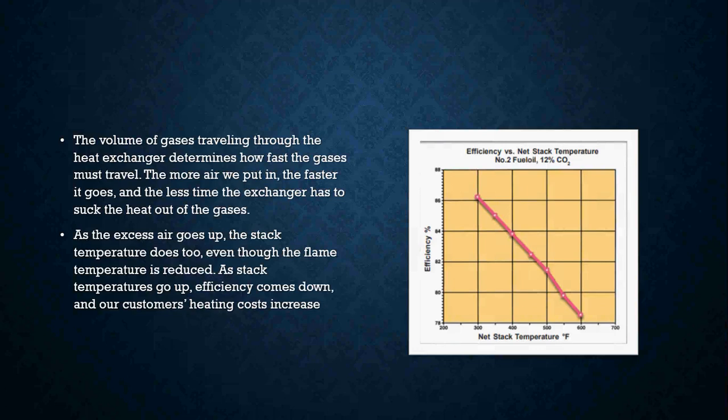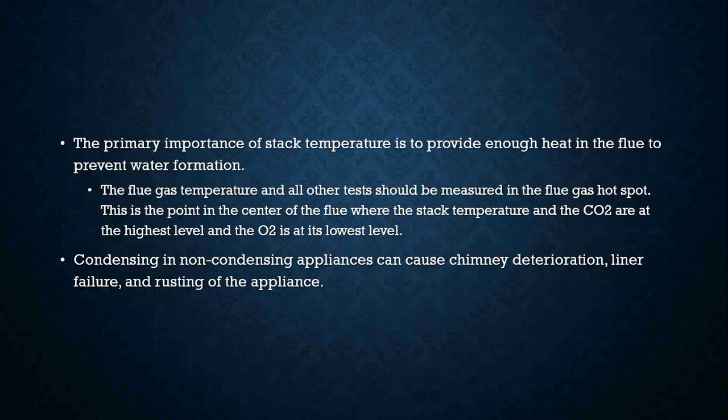So when we are doing an efficiency test, we want to try and keep our stack temperature within the correct ranges. Okay, the primary importance of your stack temperature is to provide enough heat in the flue to prevent water formation. Remember, we don't want that to happen. If we have water formation inside our flue pipe, it's going to corrode the flue pipe.